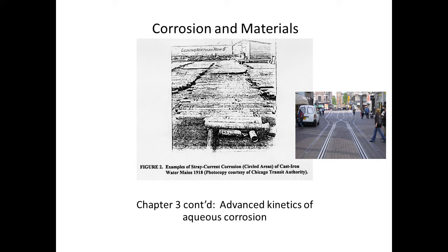Now, as far as the electrical substation was concerned, it was pulling a large DC current through the return rails, probably applying a small voltage in order to do so. And it thinks all of this current is being pulled through the rails from the train. But this is not quite true.